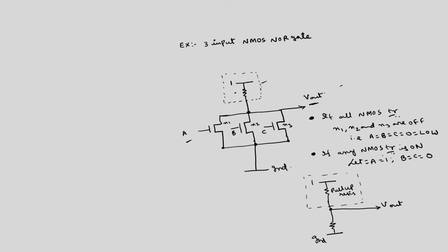Okay. So, in this case what is V out? V out will be 1, because this V out will be pulled up, okay. Whereas, in this case V out will be, so this is R n and this is some pull up resistance, okay, say some R p. This is not p type, if I use the p type then the equivalent circuit you can write this one, but this is actually pseudo NMOS, only NMOS transistors we are using, there are no PMOS transistors here. Okay.